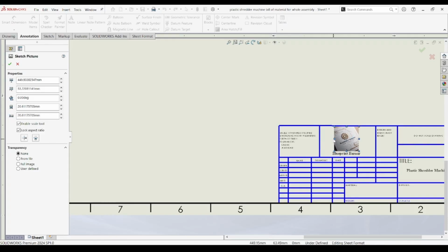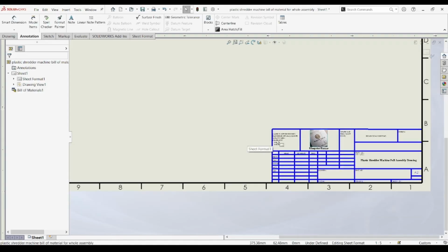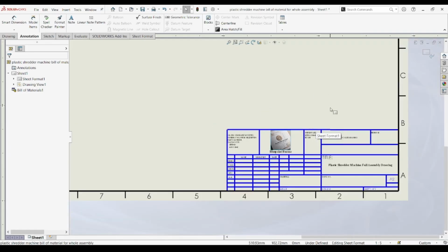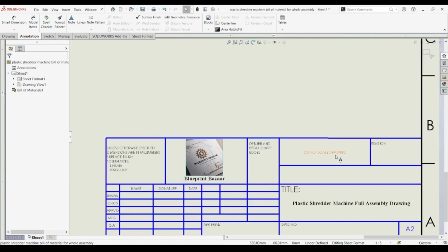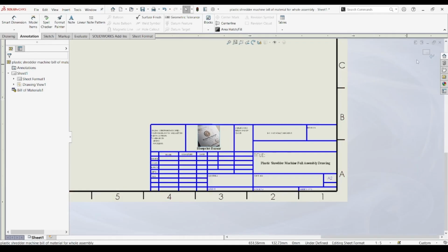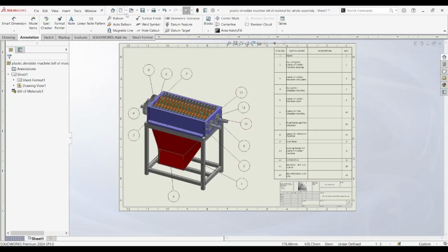Exporting is another critical step, and we demonstrate best practices for generating PDFs, DXF files for laser cutting, and DWG files for CNC machining or fabrication teams. We discuss line thickness settings, layer controls, and how to ensure your exported files meet the standards used by manufacturing partners. We even touch on watermarking, or adding for-review-only stamps for draft versions.